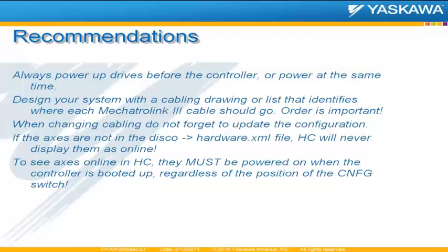So in closing, the recommendations: always power up the drives before the controller, or you can power up the system all at the same time, because the amplifiers power up much faster than the controller. The controller takes a few seconds to power up.